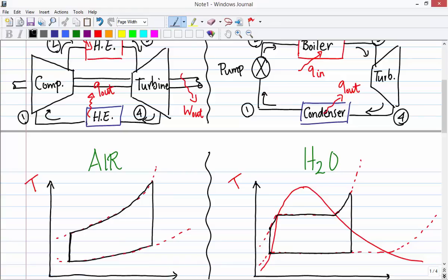So if I call that point 1 and point 2 on top of that, that would be a vertical line, and it shows that entropy is constant. From point 1 to point 2 we are at the same entropy. Meanwhile, during this process we are compressing the gas and we are injecting this work. So this is work from the compressor going into the working fluid.